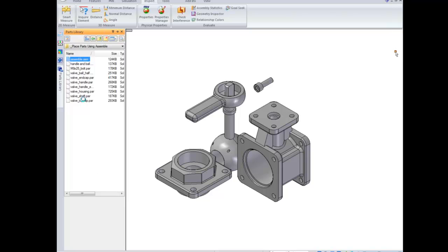Down here with our preview, we can manipulate it using the scroll wheel. If you hold it down, you can rotate around. But some keyboard shortcuts, if you hold Control over it, it brings up this menu. And it shows you that if you hold Shift and the right mouse button, you can rotate it. Control and right mouse button to zoom, or Control Shift lets you pan. So we can pan this around, zoom in and out, and get this in the orientation that we want.